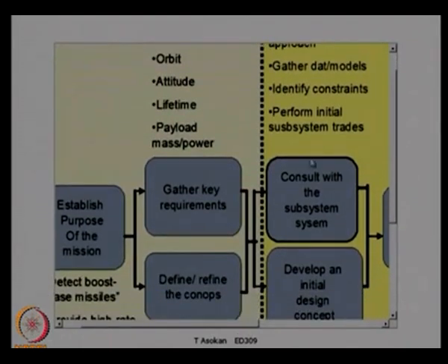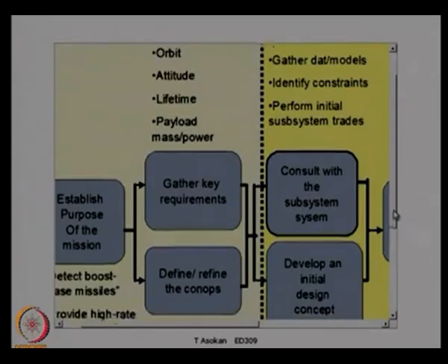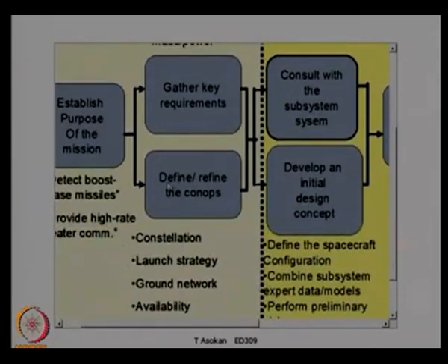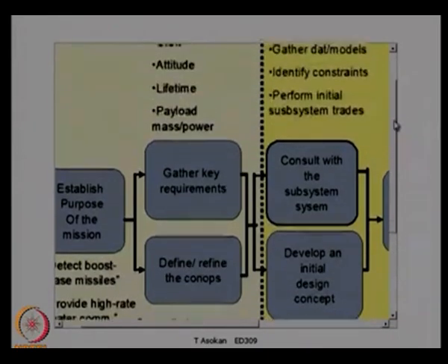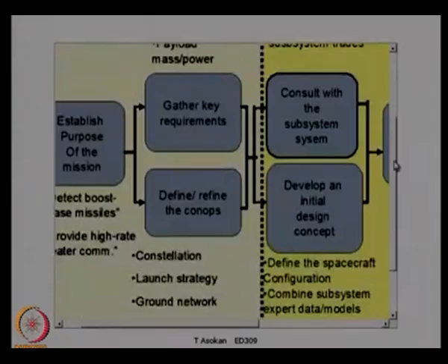the required orbit, attitude, lifetime, payload, mass, power, etc. are gathered. So the key requirements like these are gathered in this stage, and then we define a concept of operation, that is, define the CONOPS. CONOPS is concept of operations. So based on these two, the purpose of the mission and the key requirements identified for this project, a concept of